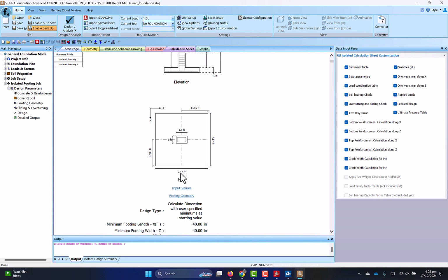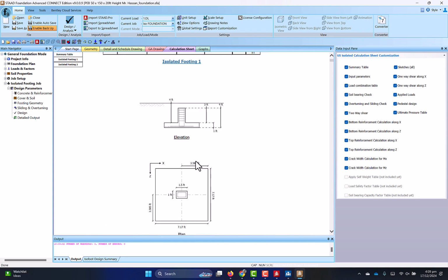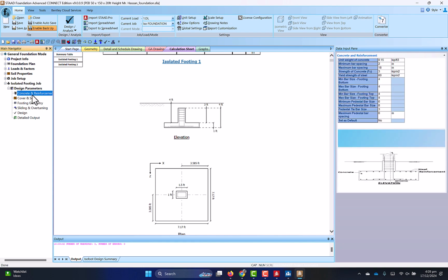In pre-engineered buildings, it's always a good idea to increase the self weight on top or the soil weight on the top. Now this is 12 inches thick. I'll probably go for a thicker one. Again, this might result in a smaller sized foundation.